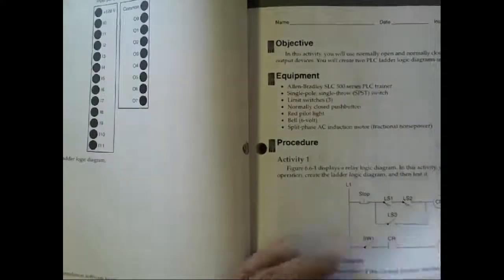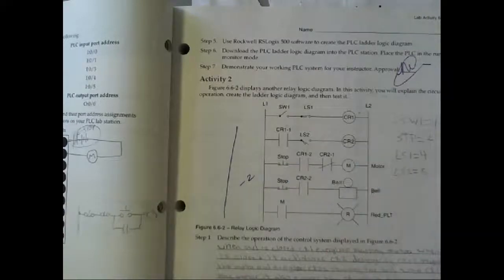So these are just standard stop buttons. But yeah, that was a good question about the E-stop, because you're going to run into E-stops. I don't know of any manufacturer that has anything in motion that you don't have an E-stop on. Robots are required to have two, one of them on a teach pendant and the other one on the controller, but they could have more than that.